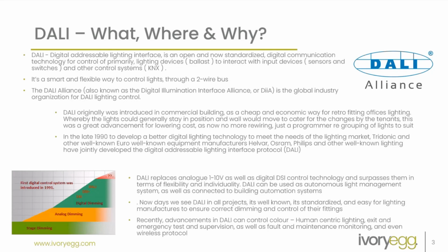It's a bus or a system where we interact with inputs, which are sensors and switches, and other systems such as KNX and other ones as we know. It's smart, flexible, and it's a way to control lights through a 2-wire bus. It's backed now by the Dali Alliance, also known as the Digital Illumination Interface Alliance, or the DIIA, which is a global industry organization of Dali control.